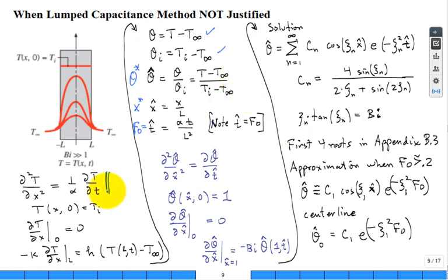So we have dimensionless time, dimensionless space, and dimensionless temperature difference. Now you've transformed that to this. Where'd the alpha go? Well, it's embedded in the Fourier number, or that dimensionless temperature. Okay, that's pretty straightforward. You still use these definitions to transform my initial condition. Then I transform the boundary condition at x equal to 0 and the boundary condition at x equal to L. Hey, what popped up in this equation? A Biot number. What's a Biot number defined as? HL divided by K.